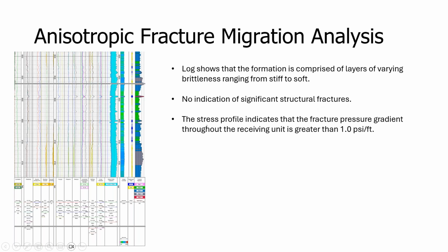In this case, the stress profile indicated that the fracture parting pressure, or fracture pressure gradient, in that zone was greater than 1 psi per foot. And if you are finding a breakover at 0.83, 0.5, or 0.65 psi per foot, which is less than 1, this analysis will help you bolster the argument that you're making to use a higher rate at the beginning of your operation.